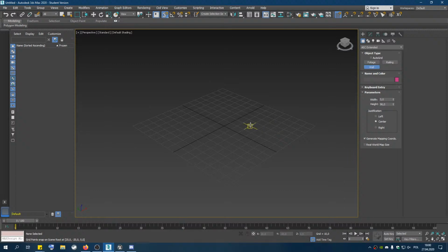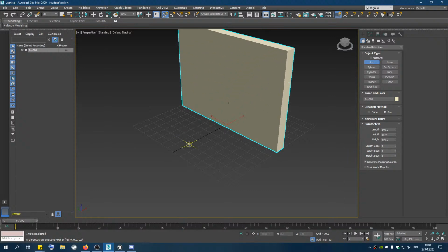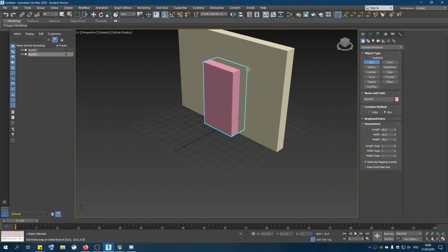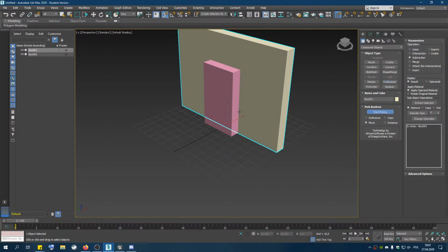So we will use the standard 3D Studio Max scale, and it will be okay, but when you create it from objects and Boolean, let me show you this really quick. For example, I'm creating a wall, then I'm creating a door like this. So I should stick to these proportions for all other objects. I will click compound objects, ProBoolean, and start picking.